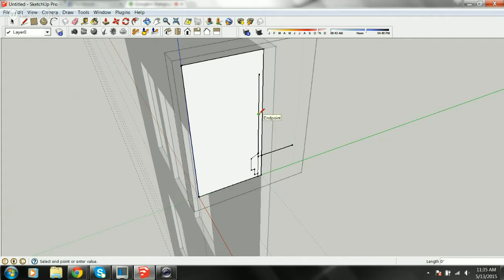Okay, so now I've got the top part of the parapet in my image. I want to come out, we'll say 2 inches with this one. You'll see how I come out and it automatically lines me up with the bottom. I love that. Got to take advantage of that stuff. Okay, we're going to come up an inch, come out another inch. Now I've got my circle, and in my drawing, I said, you know what? That's a 6-inch radius, so let's come up 6 inches. Okay. Hit the space bar to get out of it.